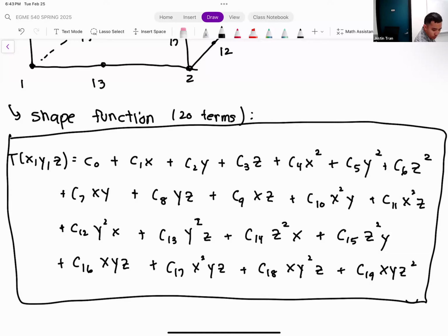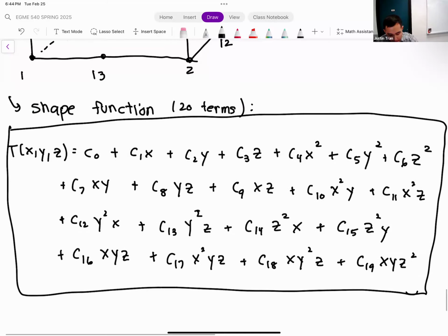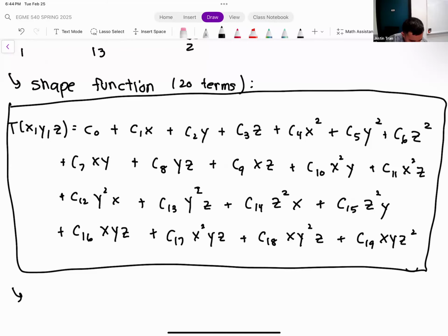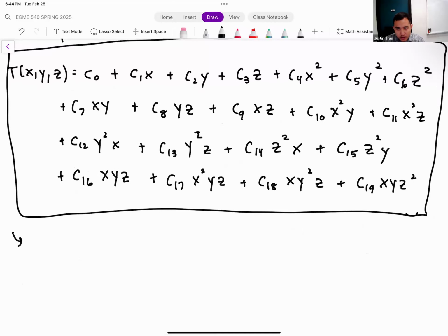Okay. So when we come back on Thursday, we've spent the majority of the time last Tuesday and today talking about element order. But we've neglected to talk about element shape or element size, excuse me. And a lot of times, element size is actually a greater predictor of solution accuracy. But it turns out element size, element shape, and element order all work together to build the quality of your mesh. So when we come back on Thursday, we're going to start with the topic, I'm going to write it down so I don't forget, which is the definitive test to see whether your mesh is good quality or not, called a mesh convergence test.